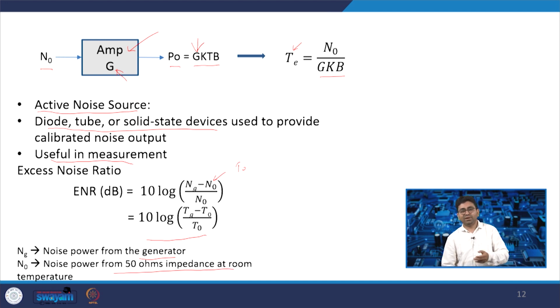This is defined. We will also see in detail, when we discuss the noise figure, how this ENR is used to find the noise figure of any device under test.